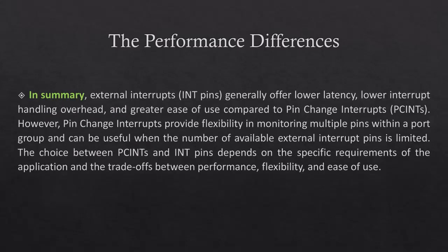In summary, external interrupts, INT pins, generally offer lower latency, lower interrupt handling overhead, and greater ease of use compared to pin change interrupts, PCINTs. However, pin change interrupts provide flexibility in monitoring multiple pins within a port group and can be useful when the number of available external interrupt pins is limited.